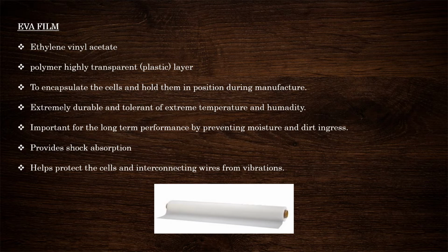The importance of EVA film. The EVA film is important for the long-term performance by preventing moisture and dirt ingress. EVA film is also extremely durable and tolerant of extreme temperature and humidity. EVA film also provides shock absorption, so it protects the cells and interconnecting wires from vibrations.